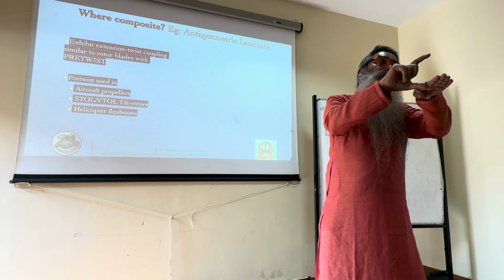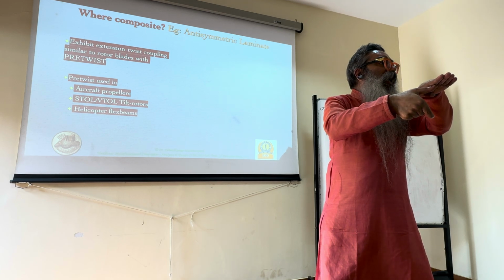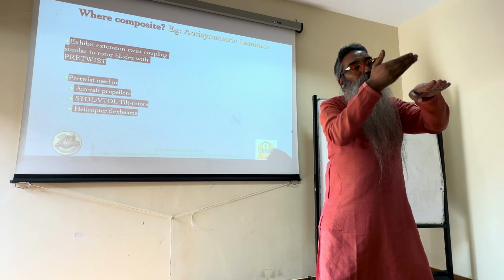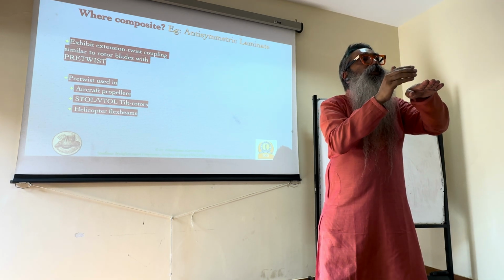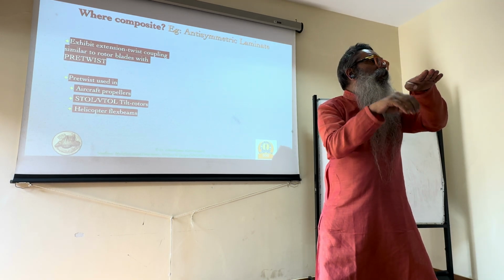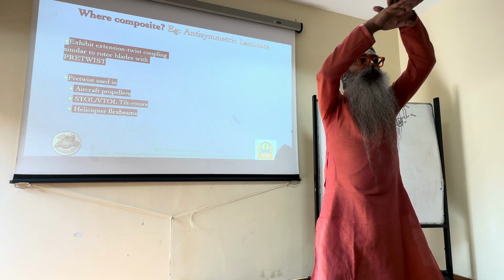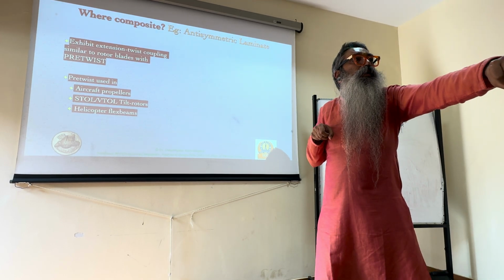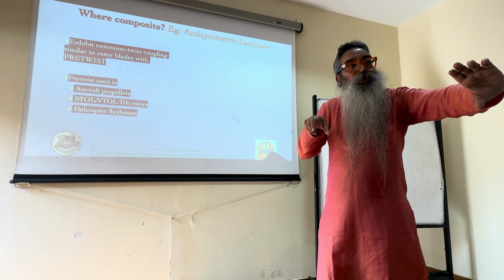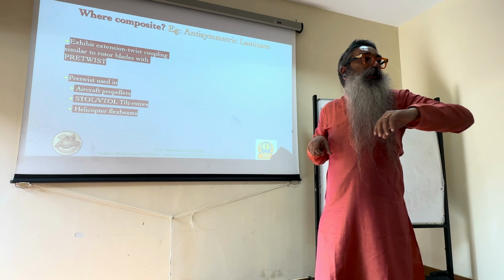At some distance here you have a minus 45, here you will have a plus 45 to balance that out, so that above and below the mid plane you are having the same set of angles in magnitude but opposite in direction, which means that you will have a bunch of fibers like this, right? So when you are trying to pull, of course it will extend, but it will also twist. If you are trying to twist it, of course it will twist, but it will also extend or contract.